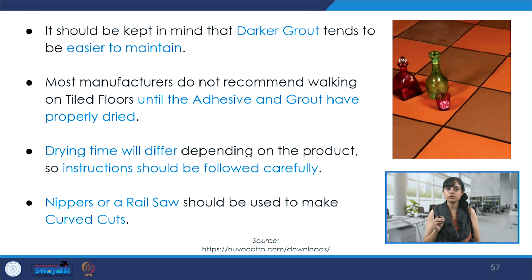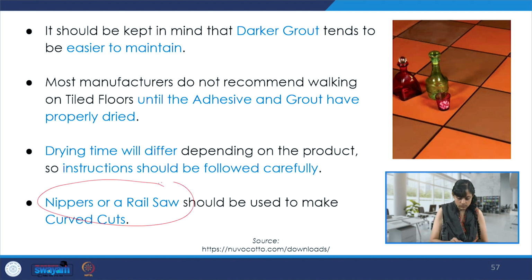Most manufacturers do not recommend walking on tile floors until the adhesive and grout have properly dried. So it's important that they are dried first. And the drying time will differ depending on the product. So it is very important to read the instructions. And then nippers or a rail saw should be used to make curved cuts. So it's not always the linear faces or just the straight cuts. It could sometimes be curved cuts. So there are tools for that also.